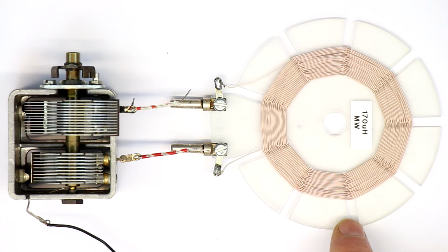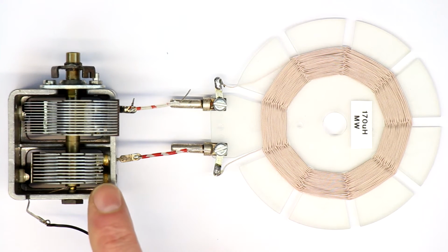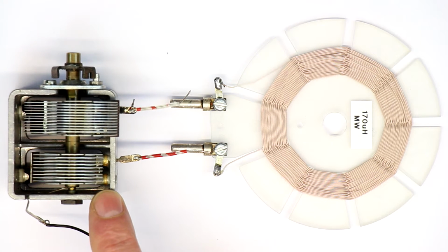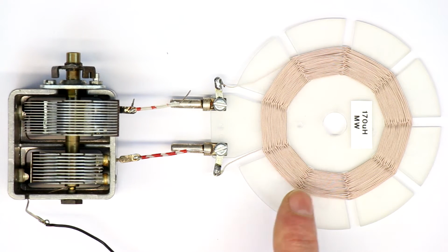And what we have learned was that the Q factor, which we want to optimize, which usually means to maximize it, depends strongly on the ohmic losses, or in general on the losses, but we can look upon the capacitor as negligible, even if it's such a capacitor with air as a dielectric. The losses happen mostly in the coil, and the first effect are the ohmic losses.